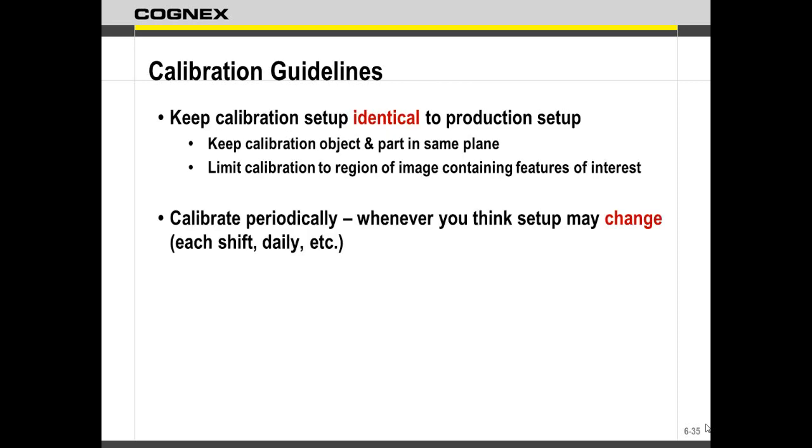Now, whenever we do the calibration, I used to joke about this in class, and now it's become a non-issue, is that we used to have flat plates that we would use, or flat gaskets. And so always someone would take, because you have your calibration plates at the end of your book, they take their book, put it underneath there, acquire it, take their book out, put the plate back down there, and it was measuring wrong. It's a different distance, exactly. You want your calibration plate to be at the level at which your part is, at the part that you're inspecting. Now, why I say it becomes a non-issue now is your book is about as high as your part. So it starts becoming a non-issue with these particular parts now. But make sure it's at the same level.